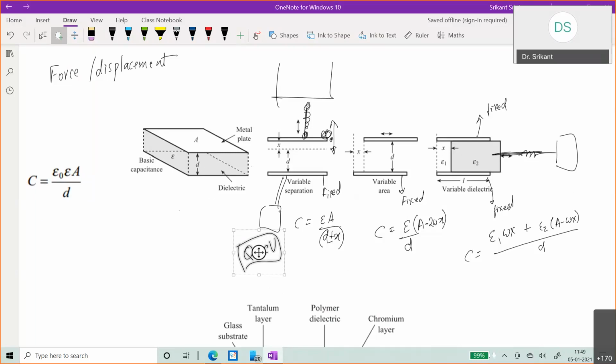Yeah, supposing it has constant charge, then by multimeter you can measure potential. Normally what happens is you cannot use a multimeter for this. The multimeter instruments are very coarse. They cannot measure such fine changes. And a multimeter usually does not measure transients. It measures only DC values, the multimeter we have in the lab.